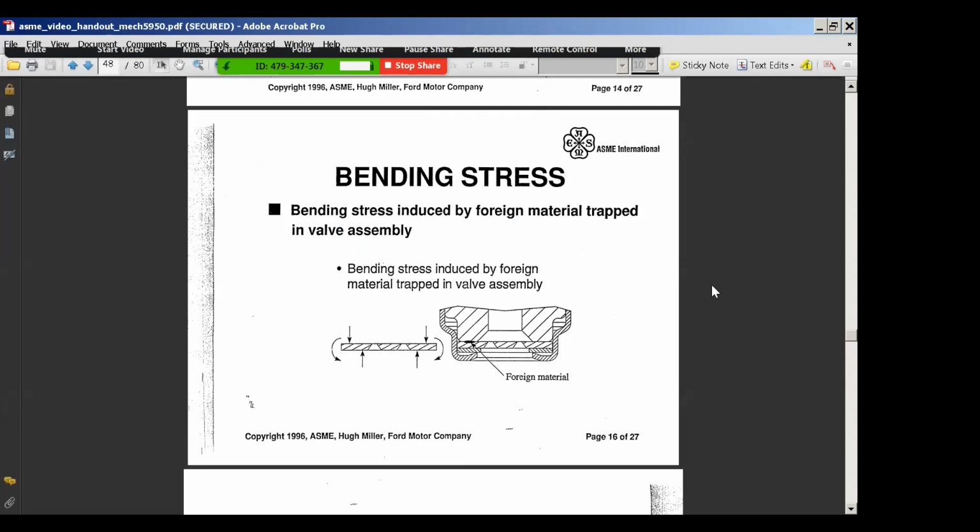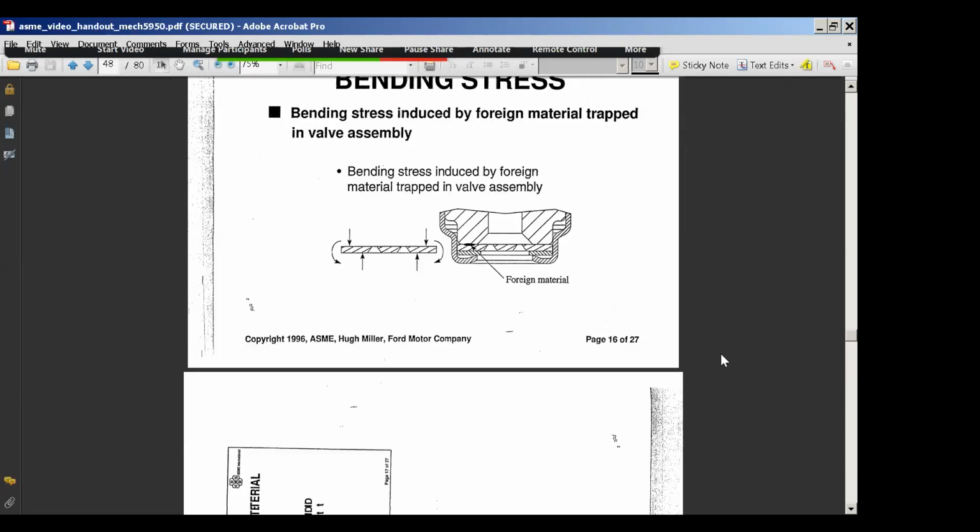Sources for this foreign material dealt with our wafer saw processing, and the condition of the nozzle as it left our factory, and handling damage that could happen in our pick and place operation, as well as in our saw operation.